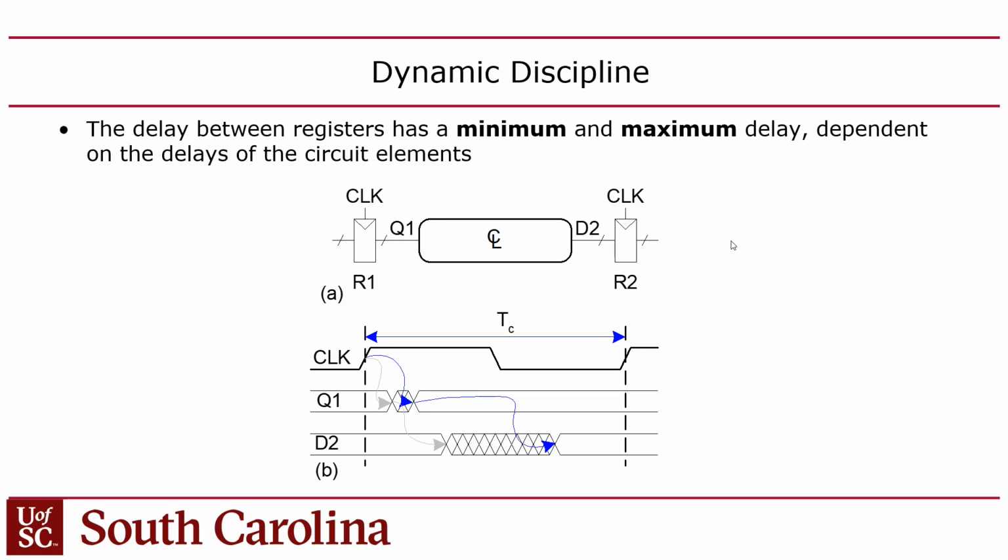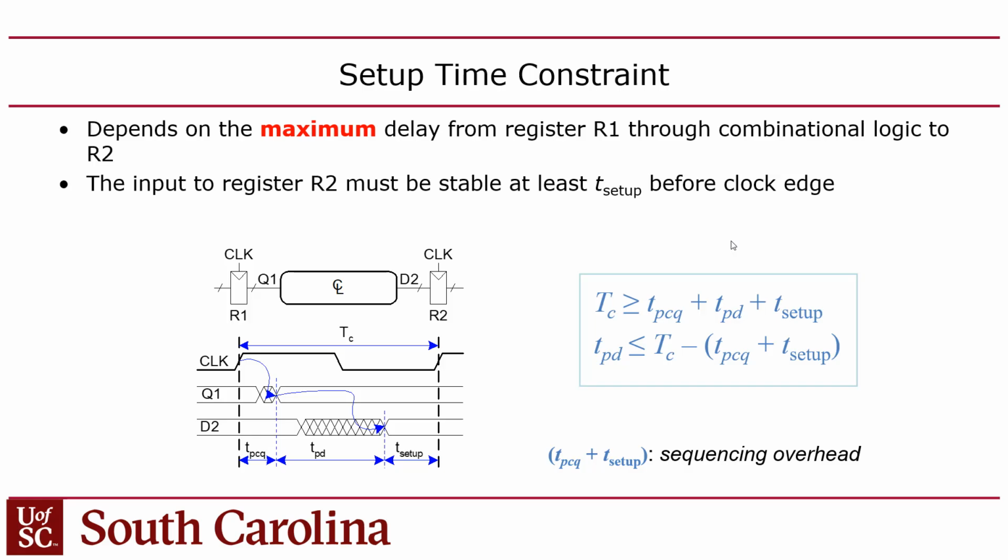But anyway, okay, so you have the clock period. The clock period is T sub C. That's another term, T sub C. That is the reciprocal of the clock rate. So at 50 megahertz, it's 20 nanoseconds. T sub C is 20 nanoseconds in your design. That's how long you have to get your propagation done, right, for your critical path. Now remember, the critical path is sometimes hard to find, hard to identify. It depends on the gate level design.